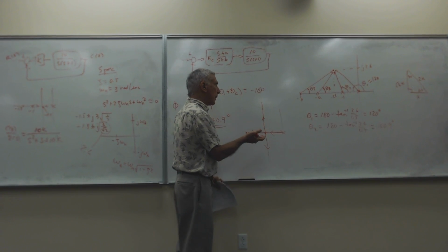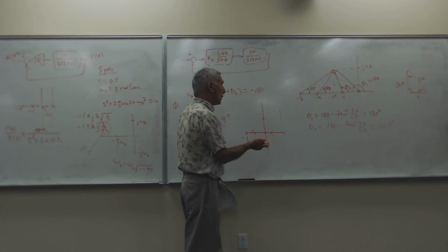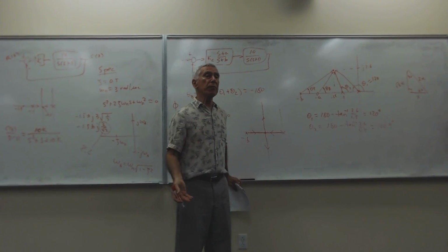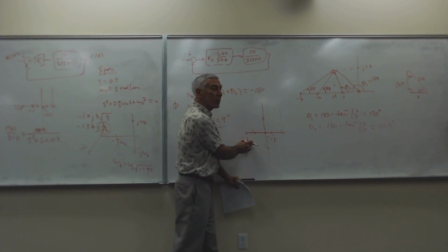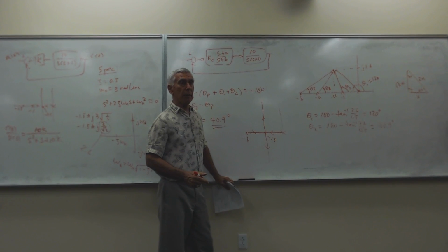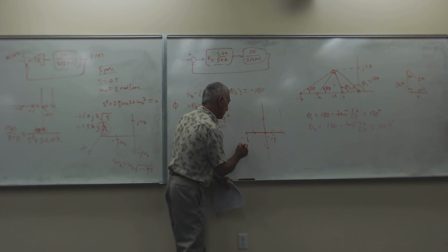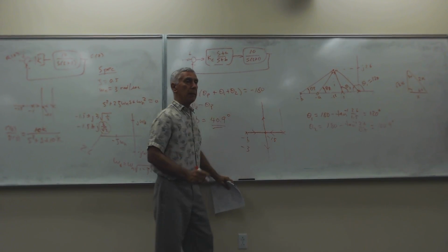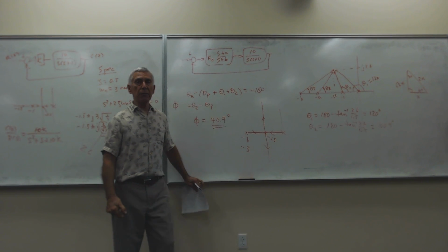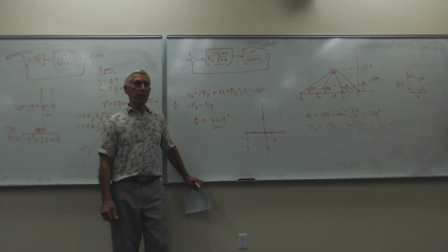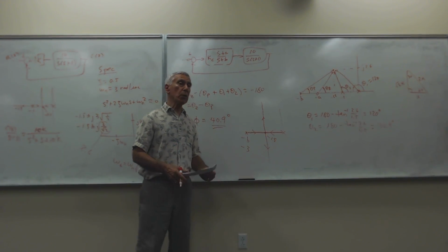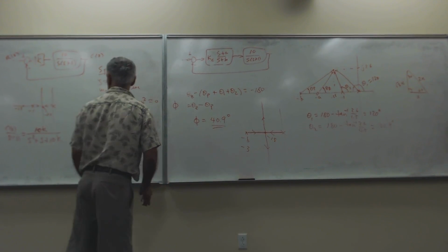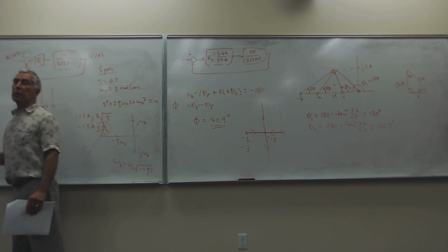And in the middle has to be minus 1.5. Minus 1.5. Therefore, what does that have to be? So this has to be minus 3. And B is therefore equal to 3. So that completes the design. Well, it's not totally complete because you have to find the K sub C here.